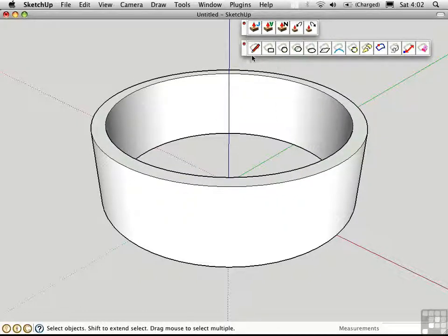Let's take a look at this toolbar. You have the Line on Surface tool, Rectangle on Surface, and so on. You can create all of these different shapes on a surface. I'll start by using the Arc tool. I'll click a point right about here, another point over in this area, and then I'll set the curvature of the arc by clicking a third point.